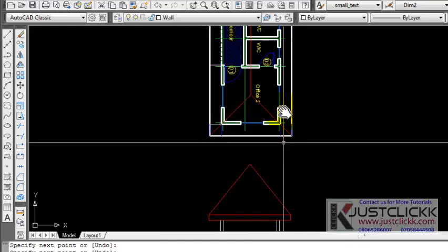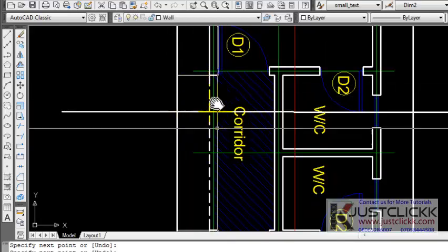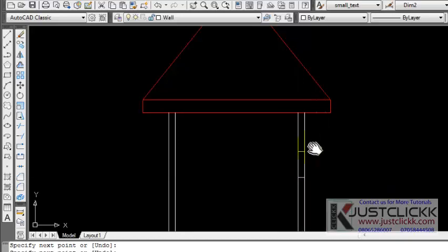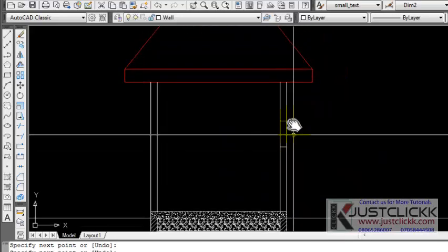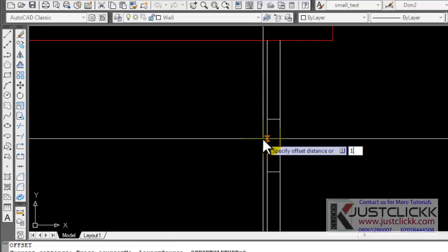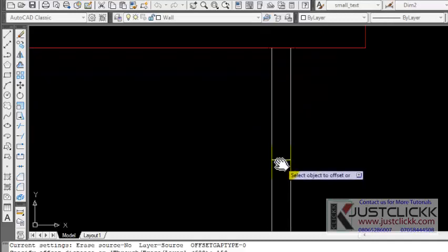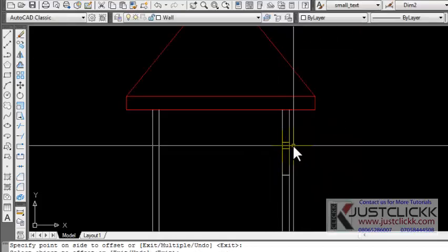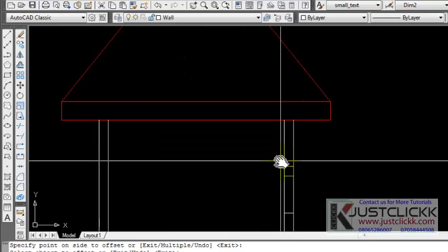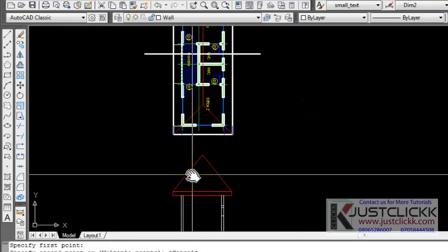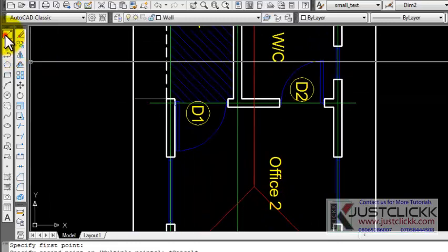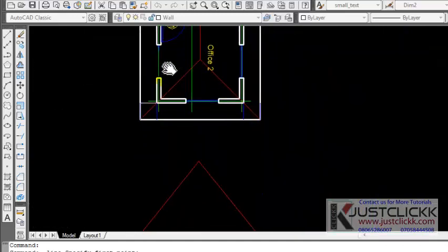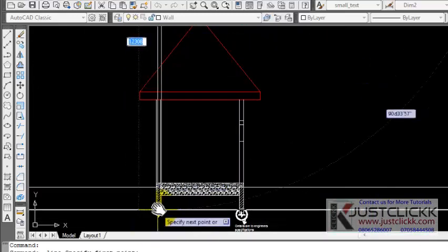Alright, so now that we have it here, we see that there is no window here. We have a window here of 600. That's what we're seeing right here. So let's offset now 150 for the lintel. We have 150 for the lintel. And let's look at the position of the door. Here, let's track it down by picking at this point where the door laps. Pick it down